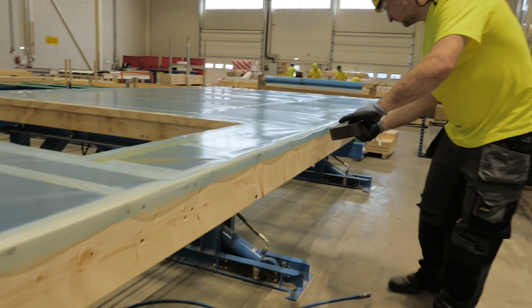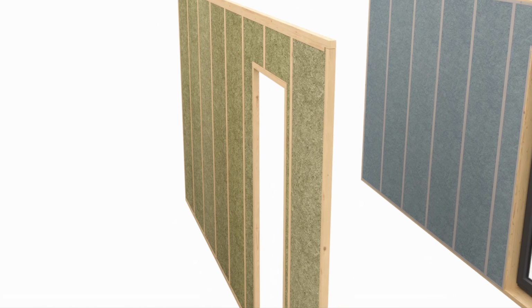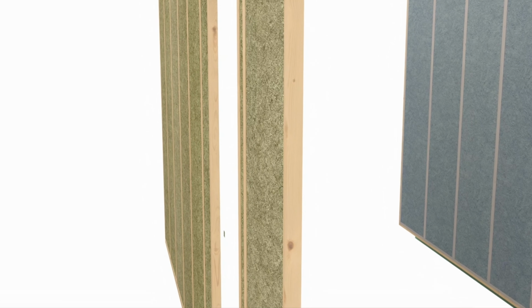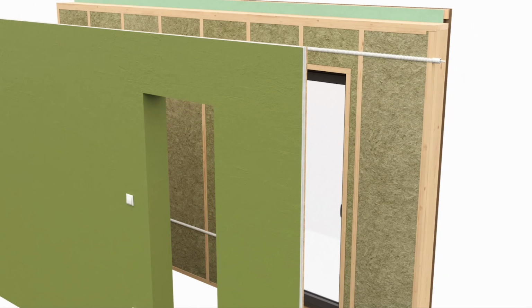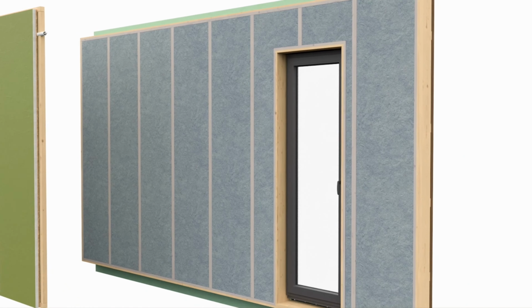Many house manufacturers use a solution where an additional lathing, for example 45 by 45 millimeters, is fixed to the load-bearing frame and the vapor barrier is between the frame and laths. In such a case, it will later be easier to install electrical installations on the wall, like cables, switches, and sockets, without fear that the vapor barrier could be damaged.